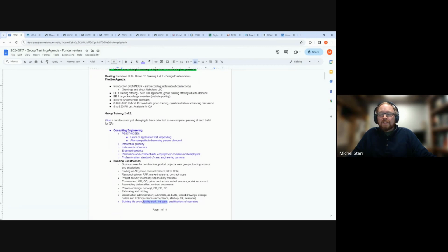So the facility staff of the building owner, they may be facility staff, or they may be calling a third party, electrician or otherwise, that doesn't normally show up. They just show up when they're needed. So it's the difference of care. And so as we're designing, that's another consideration. So like in an industrial installation, there's different level of care, or otherwise there's different allowances in the code, for instance, where disconnects can be for motors, we were saying, that are hazardous and rotating. And then yes, qualification of operators kind of goes into that.